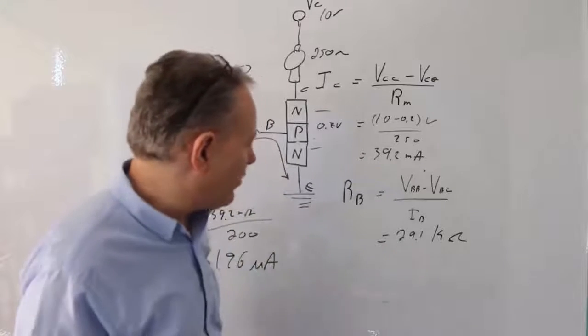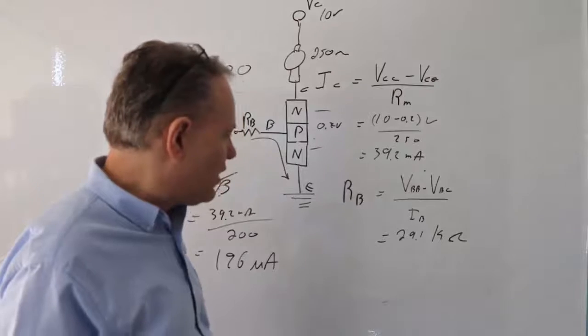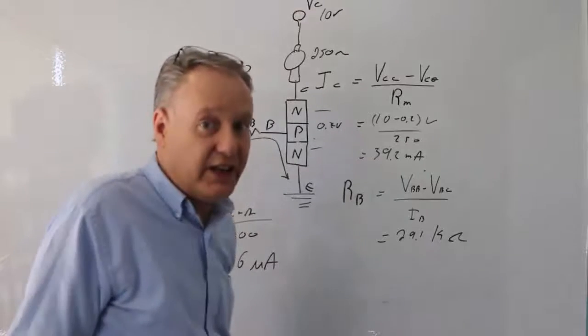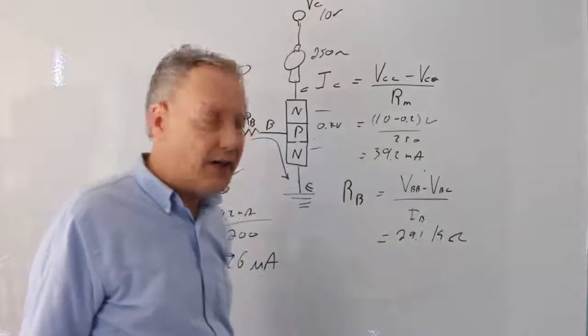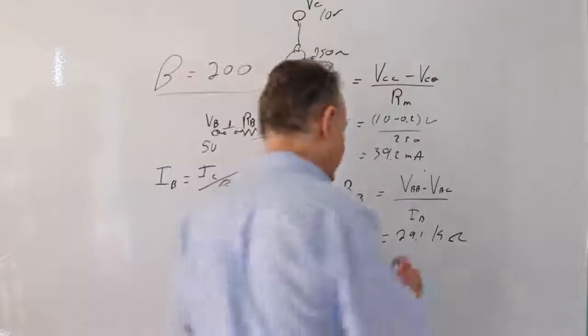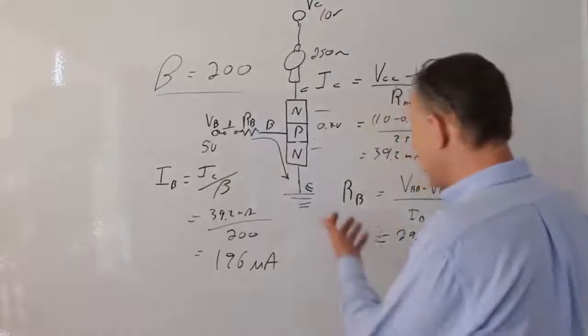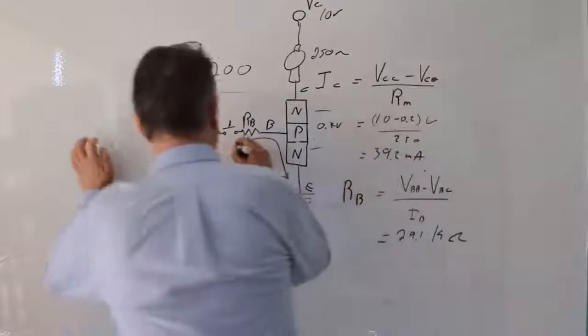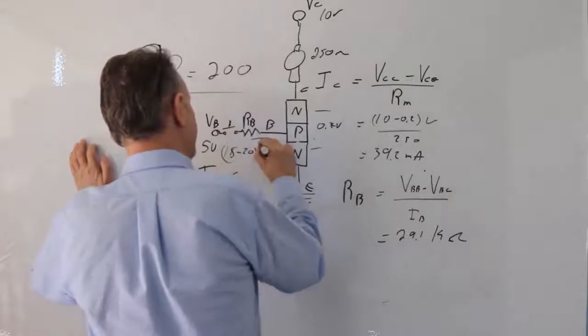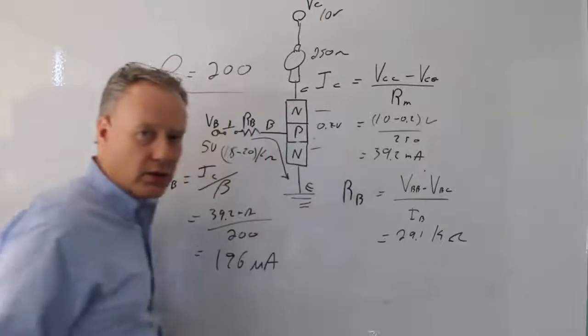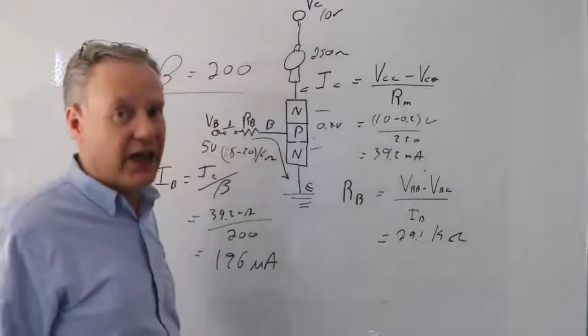So instead of 29.1 kilo ohms, I'm just going to go for like a 15K or something like that. If I put a 20K in there, I'd still be okay. So whatever's in my kit between 15 and 20K, so I'm actually going to turn this into either a 15 to 20 kilo ohms, and then I'll have definitely enough current.